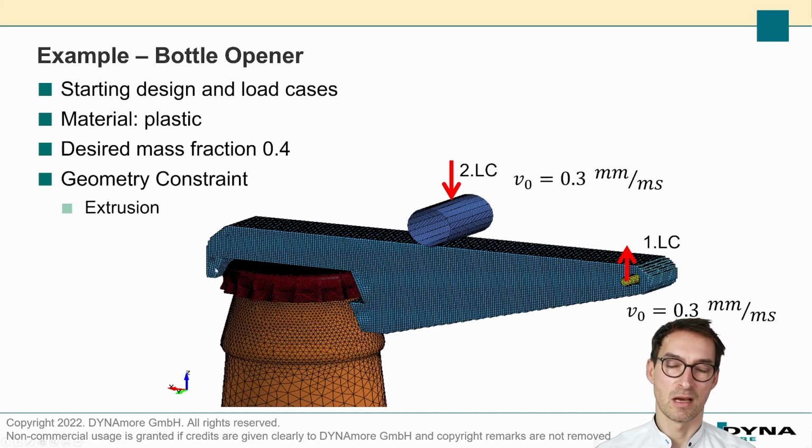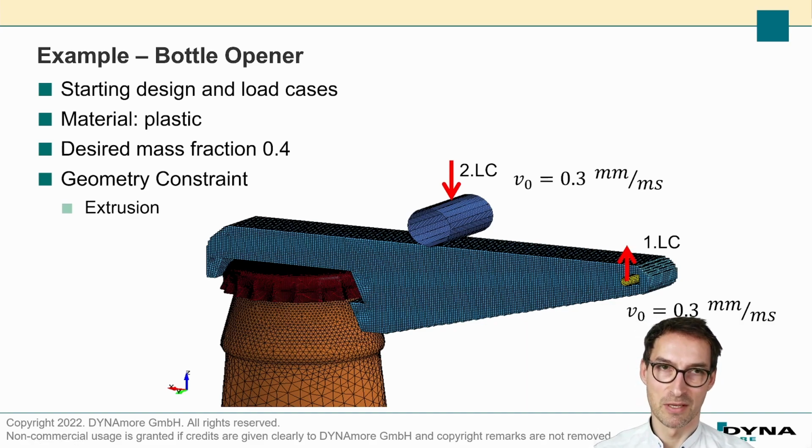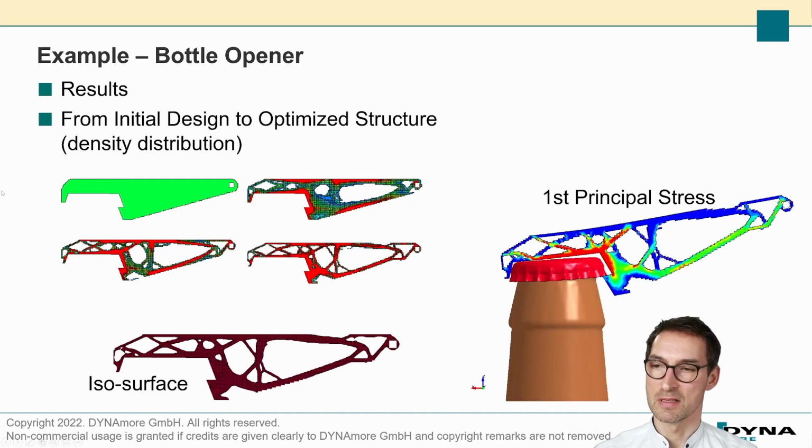And now the question is, what is the optimal design given a certain criterion? So in this case, we want to have the highest stiffness with the least weight, or the lowest weight. So this is the design space I'm giving, and then LS-DYNA is recomputing it, identifying some areas where I don't need material at all. So it means the relative density goes down in this area, goes up in this one. And then after a couple of iterations, LS-TaSC finds the optimal solution.